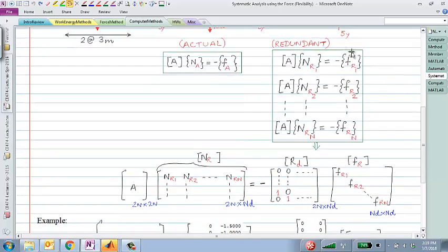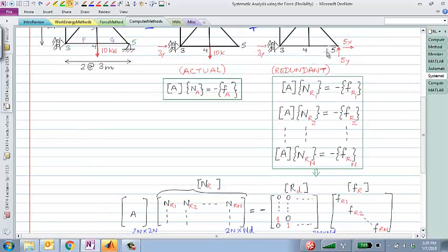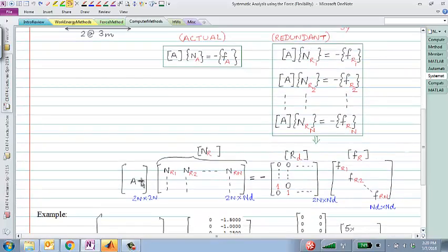And we can do this redundant problem by putting it into a loop. If you look at this closely, what we are really doing is going to the correct degree of freedom for the redundant problem, adding a 1 to that location. This is Fx, this is Fy, and we are solving for the internal forces using the same system of equations that we had before. But okay, we'll stop here. We'll talk more details about this next time.